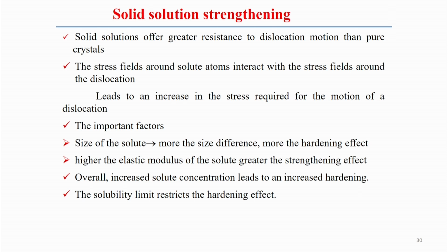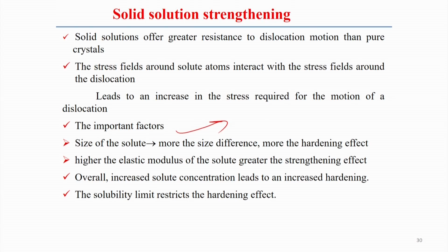The important factors in this case are, first, the size of the solute atoms. The greater the size difference, the more the hardening effect will increase. Second, the higher the elastic modulus of the solute atoms, the more strengthening effect they impart. But overall, increased solute concentration leads to increased hardening.